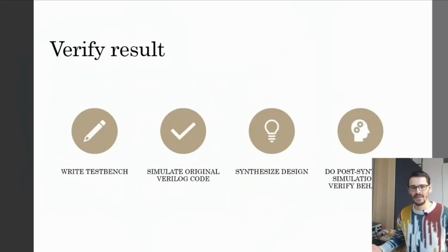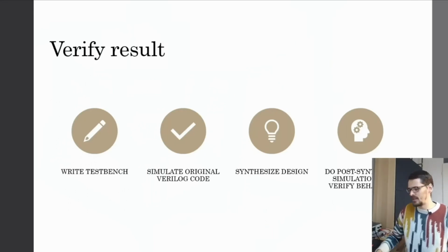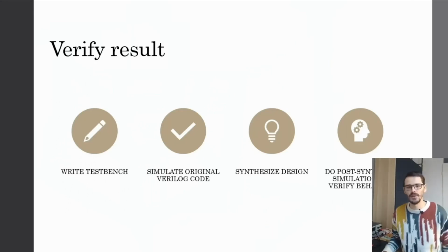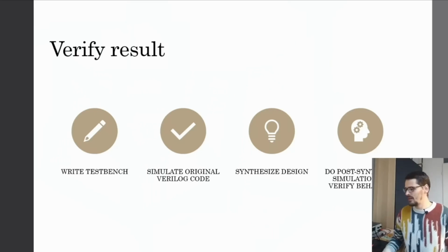And then there's a boring but important step where you verify that your thing actually does what it's supposed to do. So you write a test bench, simulate the original code, then you synthesize the design, and you do a post-synthesis simulation to verify the behavior with the synthesized version of the code.